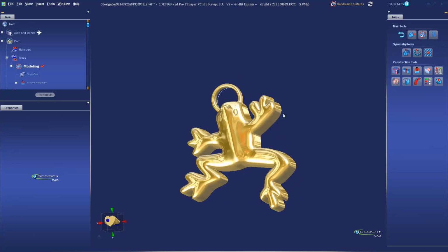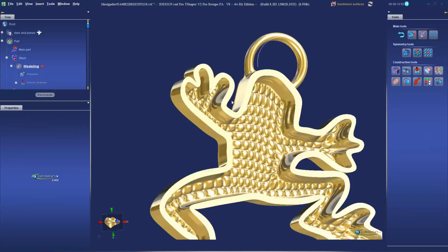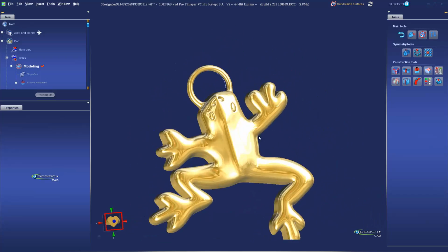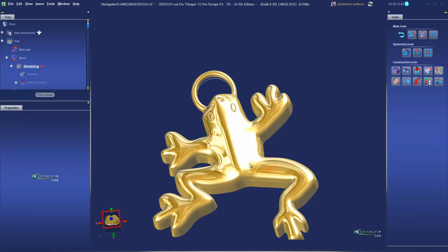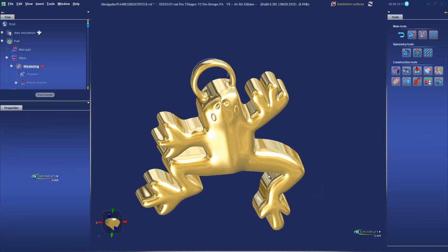Okay. Now, if you wanted to do something similar on the outside of the piece, you definitely could. Just add a little texture to it. It's a neat way to do so using the split extrusions. You can do that using colors and doing it with the parametric tool, or do it right with the regular extrusion tool.